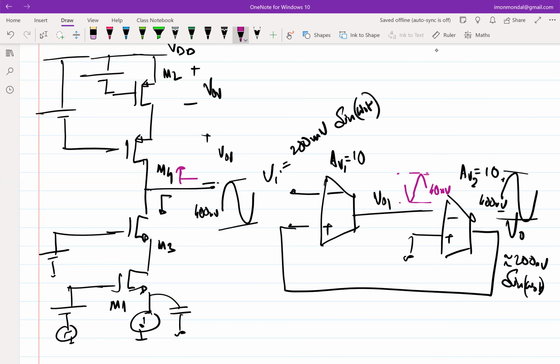So when it comes to 0, you know that it's probably some second order or first order effect that you are neglecting. So you go back and figure out how much the difference will be. Approximately this is 400 millivolt ideally, but it will be divided by the loop gain. The loop gain is 100, so probably we will have 40 millivolts at the input. No, I think I made a mistake.